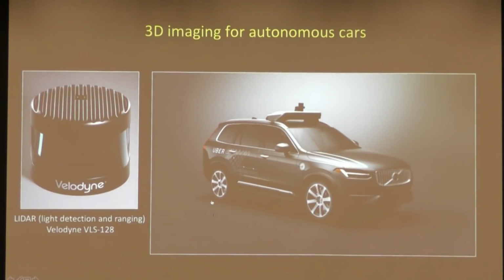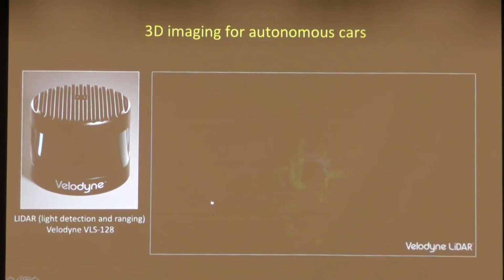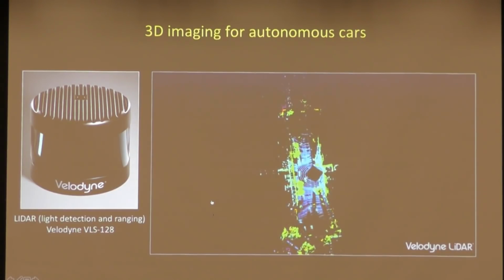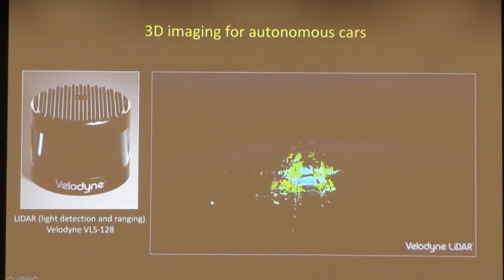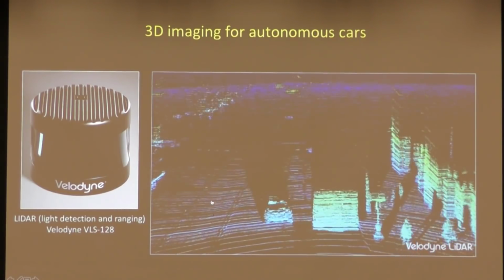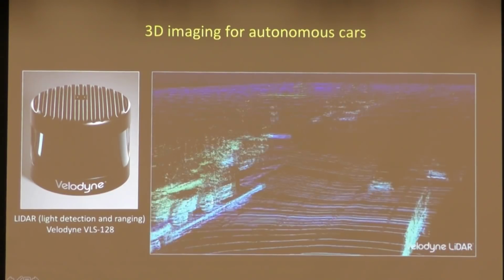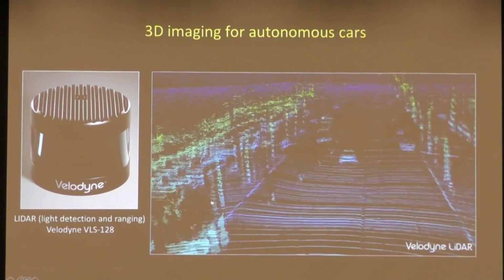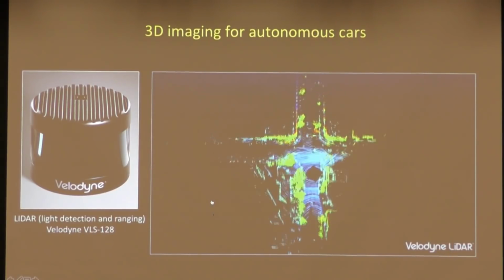So a LiDAR system, or a light detection and ranging system, is often found or paired with self-driving cars, and they're used to capture point clouds representing an environment. And this works basically by sending out these pulses of light in the environment and measuring the time it takes for that light to come back. Now, usually this doesn't involve SPADs. It uses something known as an APD, but it operates on a very similar principle. Now, SPADs, though, have some characteristics that potentially allow for these LiDAR systems to see even further and at higher resolutions and at faster speeds than in existing systems.